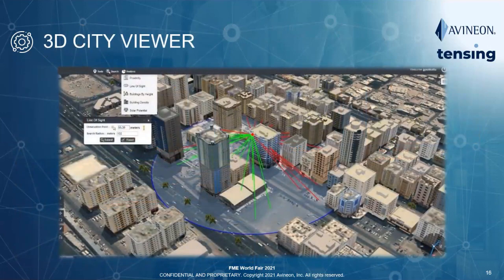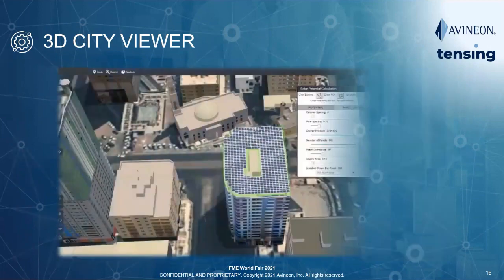The viewer supported the multi-patch textured models, and so you can do this advanced spatial analytics. It also supports CityGML modeling, and you can see here, for instance, line of sight analysis. So you can do point-to-point or area-based options. Inside this web application, you can change your elevation, you can do proximity analysis. It'll give you a detailed list of buildings, and everything is integrated with the building database.